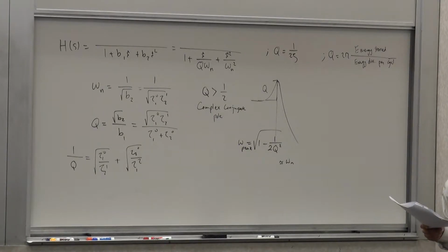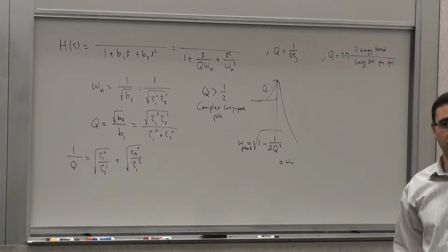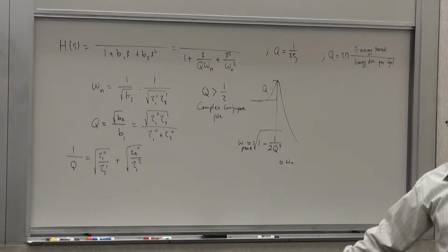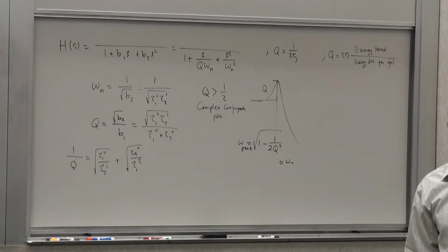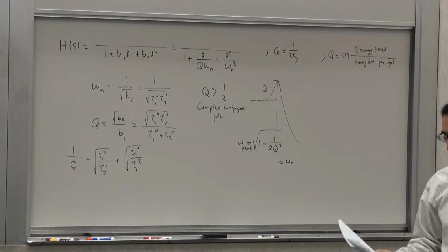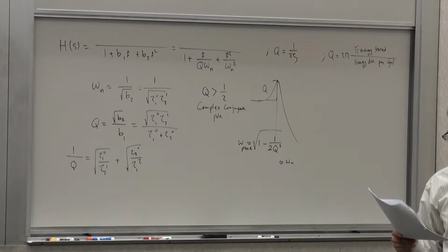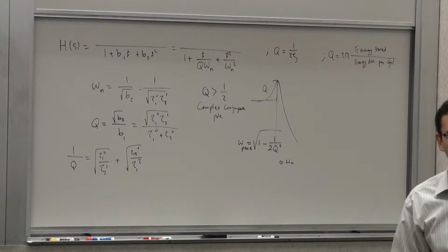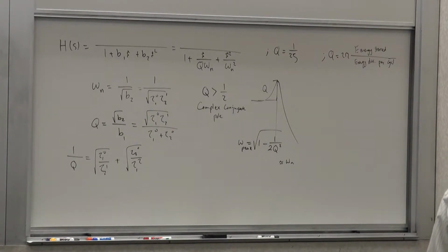For regular poles, like real poles, the curve goes from a decade below to a decade above for 90 degrees of phase. So here it goes through like 160 degrees of phase over a very, very short distance, like a tenth of a decade. So that slope tells you that you have very underdamped poles.